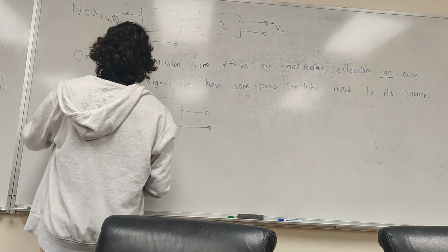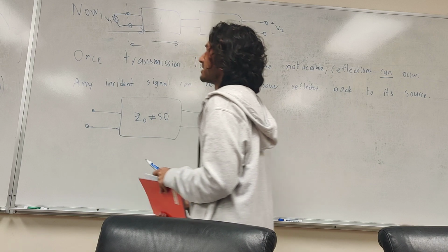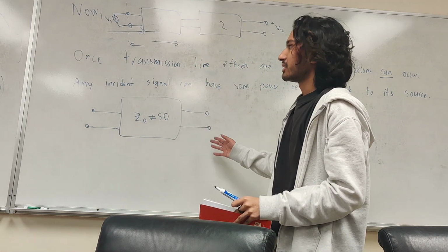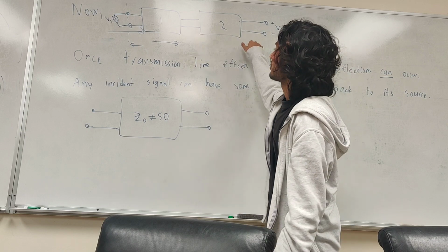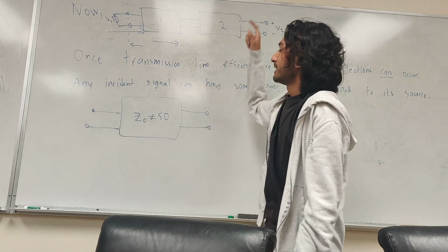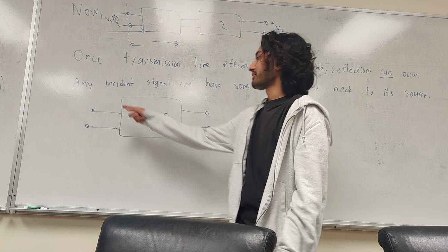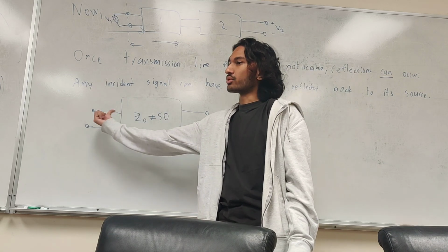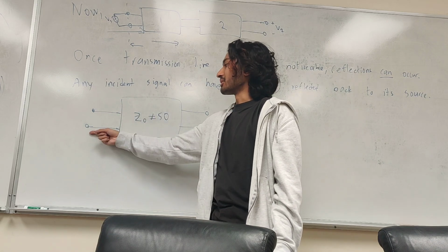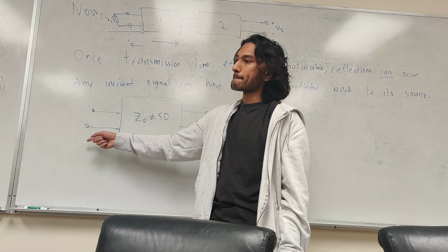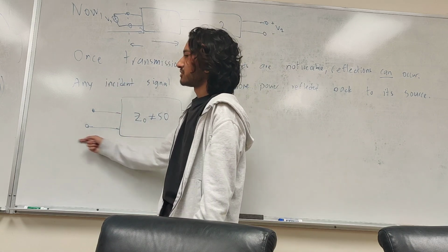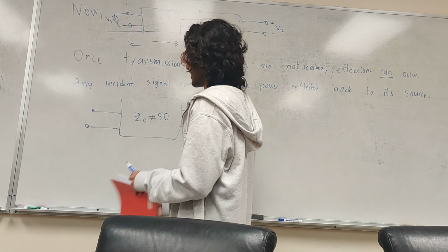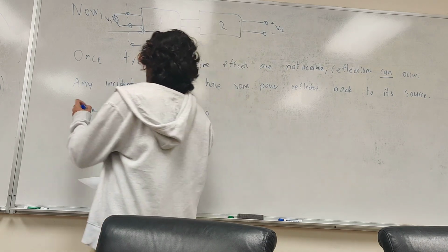So, the other kind of confusing thing I'm going to draw here is the way these signals are represented. Before, we were like, oh, these bottom two are ground and our signal's up there. What we're going to say for S parameters now is one of these terminals is for forward waves, and the other terminal is how our signal gets reflected. So we're going to just say signal goes in one way, and there's an explicit terminal that it comes out through, just for the sake of displaying what's happening.